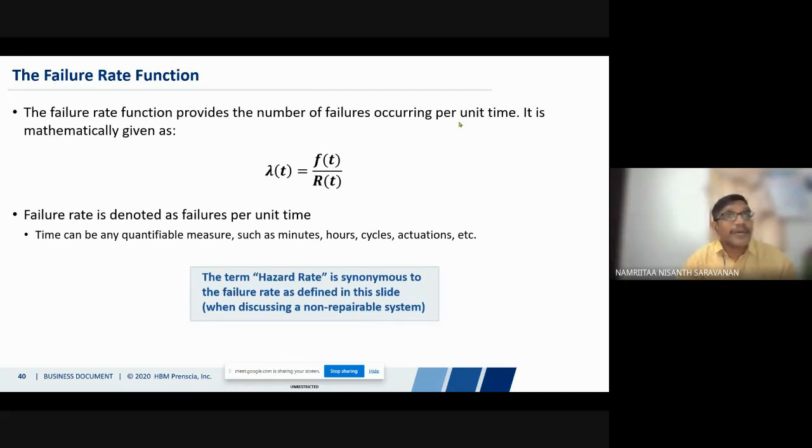The reason is the person who installed the fan forgot to install the quarter pin in the bolt. So what happened is, when the fan keeps on running, keeps on rotating, the nut becomes looser. The bolt comes out without the quarter pin because the person installed the fan without it. So these are the maintenance problems. In such a way, the hazard rate is something similar, connected with the safety point of view, if you think about that.